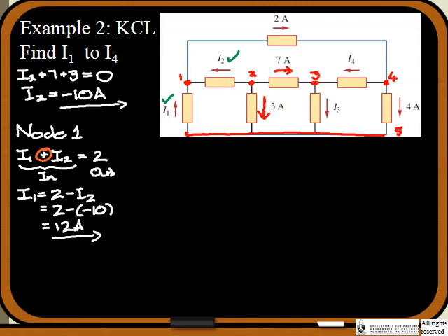So now I2 goes in, I1 goes in, so there's 2 amps. So let's just perhaps, yeah, so that still holds. Next one we can solve for, it seems, will have to be I4, because at I4 there's only one unknown. So now we're going to node number 4. We're going to write this one. Let's just drop this one down. Keep that separate. So let's work at node number 4, because there's also only one unknown.